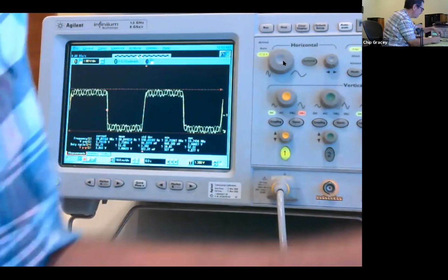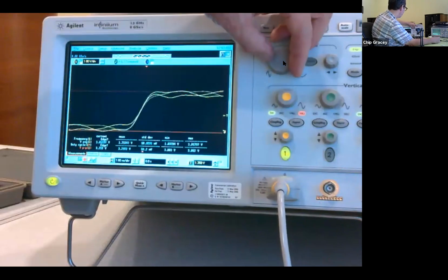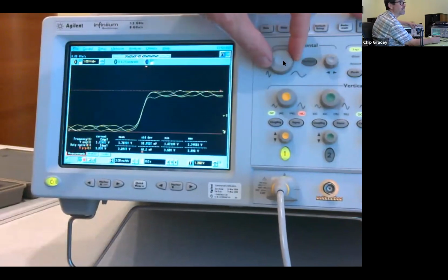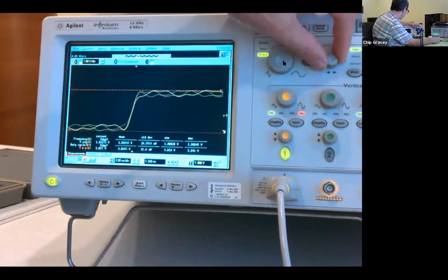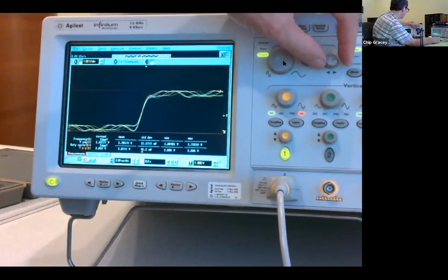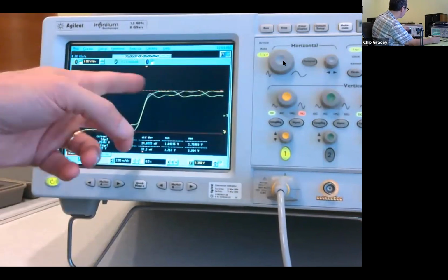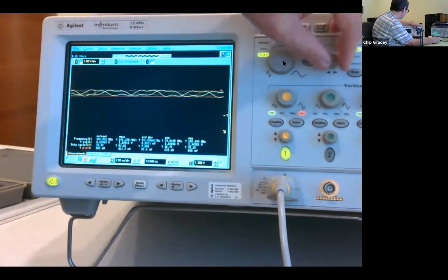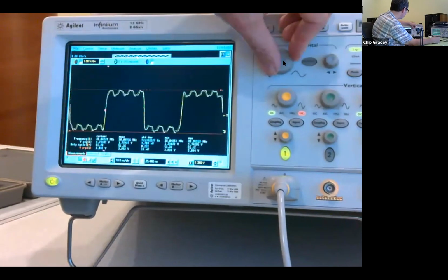Anyway, we can see though that now instead of a sine wave going into XI, there are very sharp edges. If we zoom in here, we're at 1 nanosecond per division. This is 2 nanoseconds. So we have a rise time of maybe 1.5 nanoseconds, so it's a lot better than before. Before we had a slow moving sine that could be interrupted, but this slews past the logic threshold so quickly on either side that there's no possibility that it's going to be disrupted.